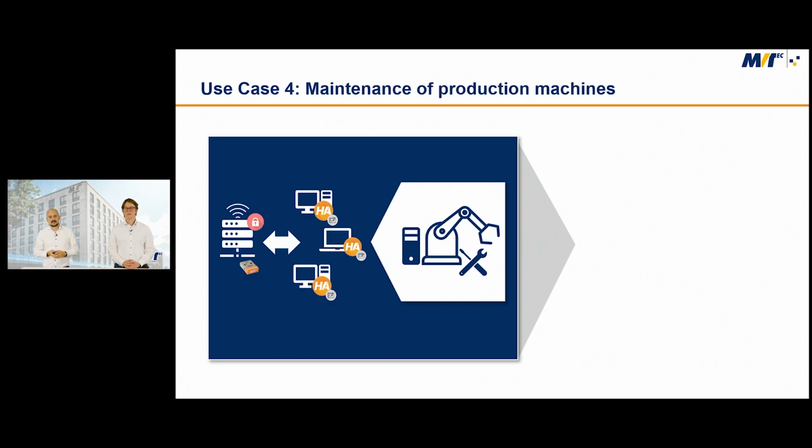Now with the license server, you have the possibility to set up one license server, or one PC in your production line, as a license server and put the floating license there. Just in the cases you need this SDK license, you can open it on every connected PC machine and use the license via the network to run HDevelop.